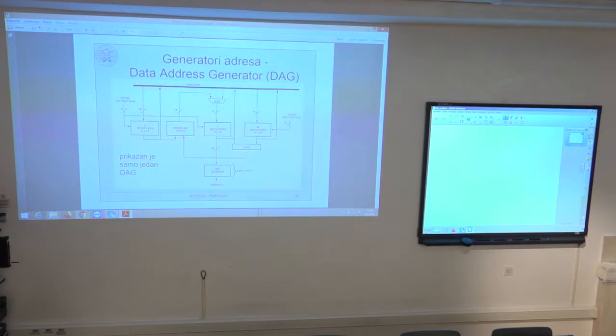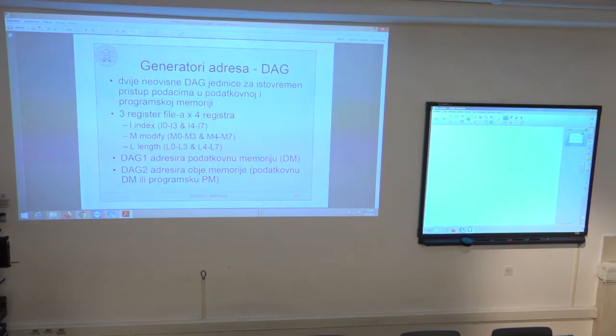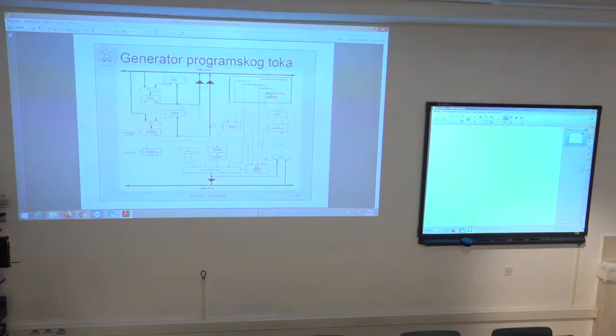So this can be activated, and after activation of this bit reversal logic, this addressing will automatically be behaving as desired for efficient implementation of fast Fourier transform, for addressing of the arguments that are read from this buffer. Okay, that is regarding these data address generators.